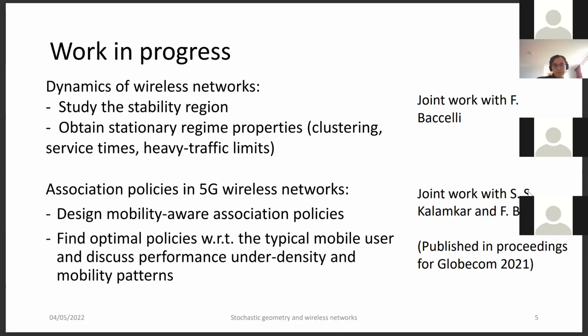And yes, the base station is static. The beams are static also. There's no tracking. And when the user is moving, you have a beam boundary crossing. When there's a beam boundary crossing, you have a small amount of time in which the network has to update the beam to which the mobile user is connected. This acts as a limiting factor, because if you're moving too fast, then you always have to reshuffle between the beams of the same antenna. This is how we managed to prove that there is actually a maximum.